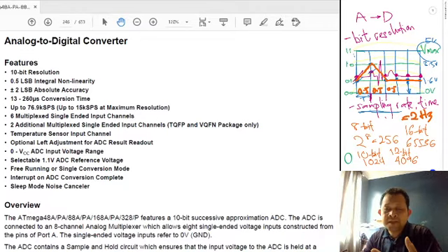So you can have many bit resolutions, as high as possible. But the thing is cost. When you need more memory, you need to add memory, so memory is cost. And then in terms of technology also, how capable is the current technology? Technology 20 years ago is different from technology now. Now you can have 24 bits, but 20 years ago, you saw mostly around 16 bits. 20 or 40 years ago it was up to 20 bits. But as technology progresses, you can have more bits, 24 bits.